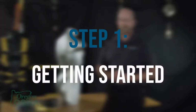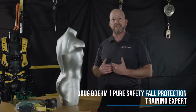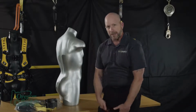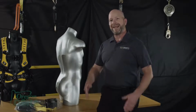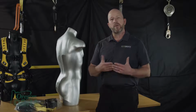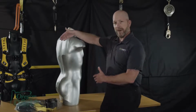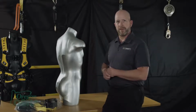So let's talk about some of the components of a personal fall arrest system. We'll start with the harness. All harnesses are designed so they have some basic elements. They must have shoulder straps, chest strap, a leg or thigh strap, a subpelvic or a pelvic strap, and a waist component. And the waist component is the fact that on a harness, the front becomes the back and the back becomes the front, and it will cross over, as you'll see once we fit the mannequin.